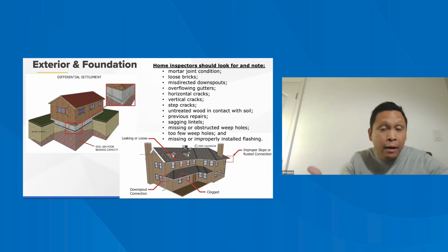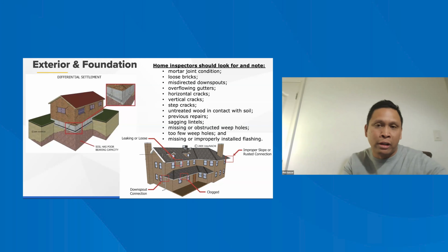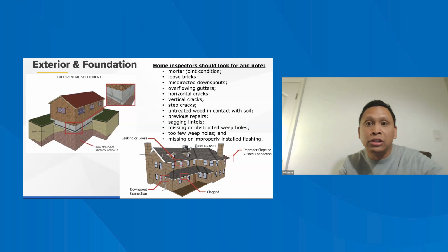Stand a little bit further away. Make sure that wall, or the wall next to it if you're next to a corner, is not moving. Make sure it's not leaning. Make sure it's not a bigger condition that's actually creating the smaller condition that you saw. Because a smaller condition with a leaning or moving wall, all of a sudden it's, oh wait, that could actually be a pretty large condition.